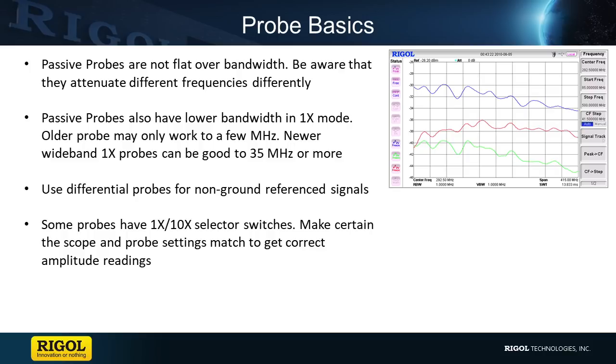And then your probes here have what is called a 10x 1x mode switch on them. The 1x mode gives you the exact right voltage on the output of the probe as the input, 1x attenuation. That is really limited to probably somewhere between 7 and 50 megahertz. So on that setting, it's really made for low-level signals, like millivolt level signals at slow speeds.